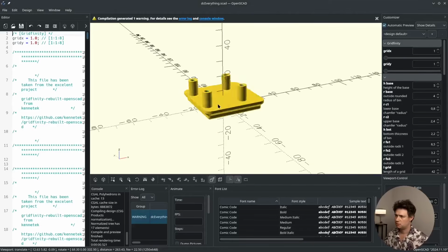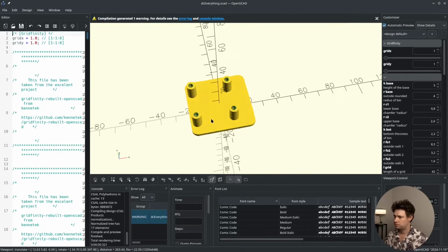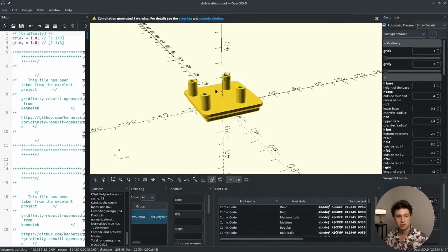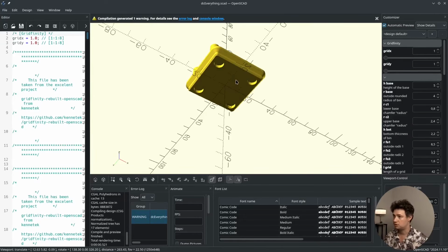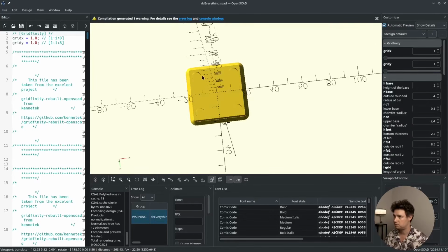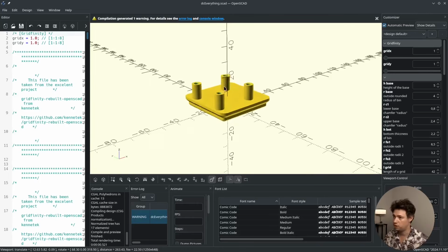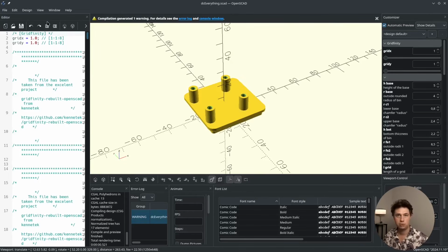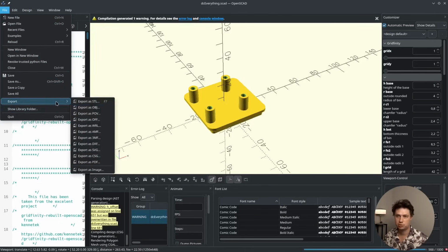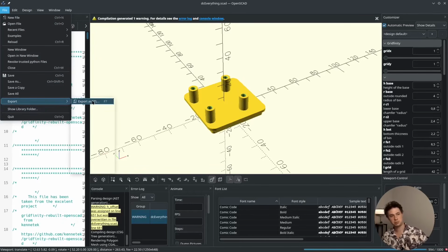If we let the turbocase script run with the walls at a size of 0, we can actually get something like that with the Gridfinity template below that matches the holes that we need, 3 holes in that case, but it can be whatever you need. And now all we got to do is to actually render and then export as an STL, and let's print that.